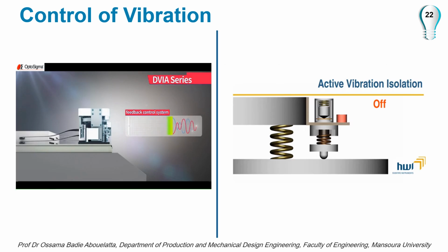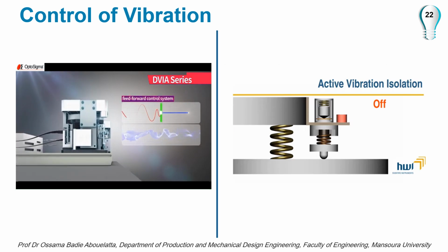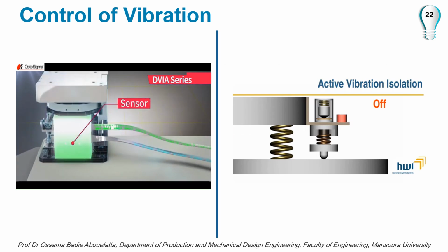Sensors record vibration inputs in all 6 degrees of freedom, while a digital control unit converts the measured vibration data into digital signals. The controller then sends these signals to the actuators, which cancel out the vibrations and create an equal and opposite force.